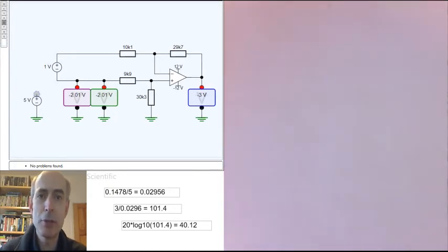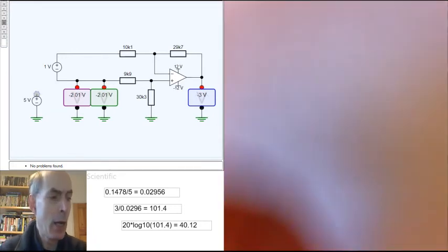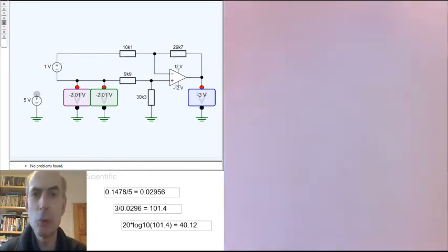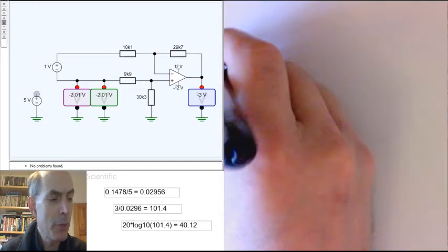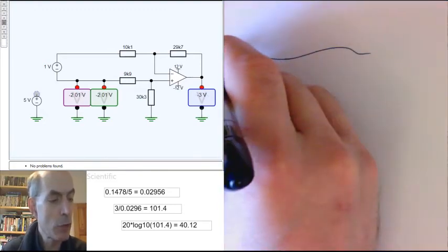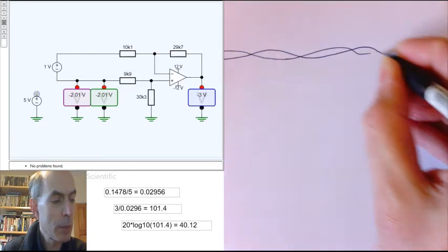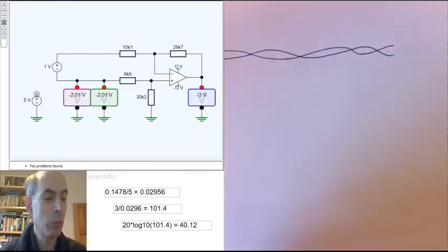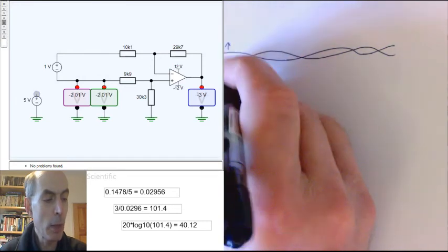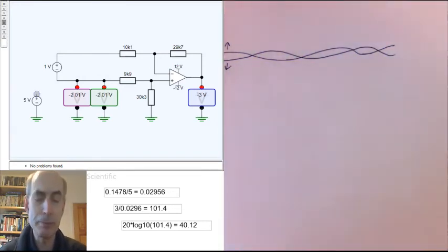It might be worth saying a bit at this point about why there is a specification for the common mode rejection ratio of these amplifiers. And the answer is because it gives you a specification on how well the input stage rejects noise. Quite a lot of the outputs from audio circuits, from high sensitivity microphones, are very, very small, and they are sent over cables in differential mode, which means that you've actually got 2 signal wires in the cable, one of which is going up while the other one is going down, and vice versa.